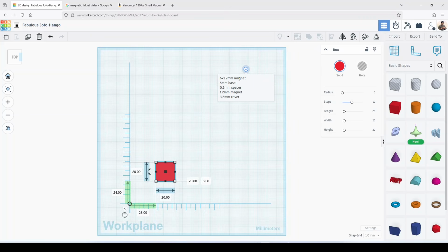So essentially what it means is that the left and right margin of your tray, or the base, is going to be both 6 millimeters, and then your magnets also 6 millimeters, and with the space between the 2 columns of magnets, 6 millimeters. If you are following me still, then you will know that we have 5 units of 6 over here. That means that we have 30 millimeters of width. So let's quickly switch to 30.